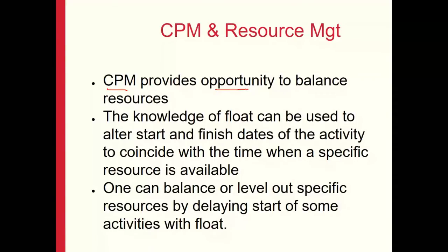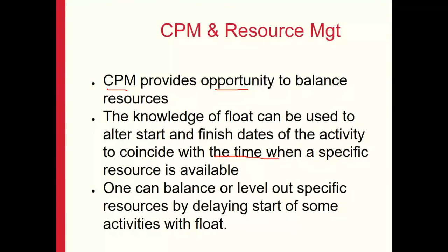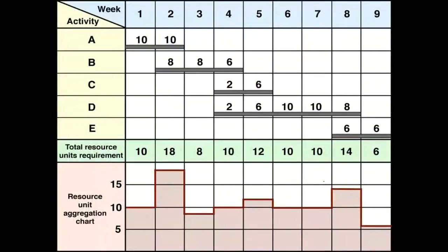Now, the knowledge of float can be used to alter start and finish dates of the activity to coincide with the time when a specific resource is available. One can balance or level out specific resources by delaying the start of some activities with float, and I think this will become more clear as we do a few problems.